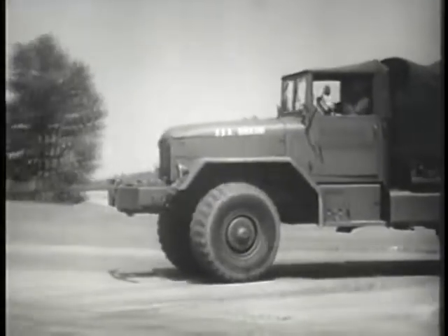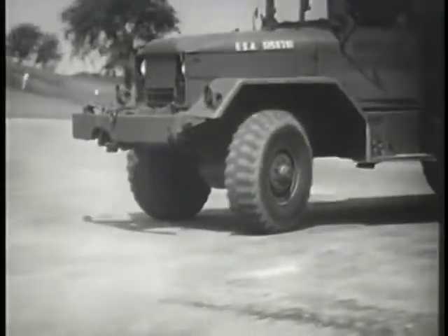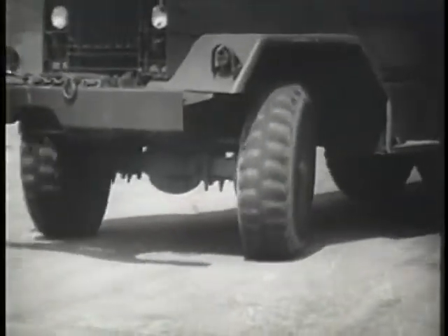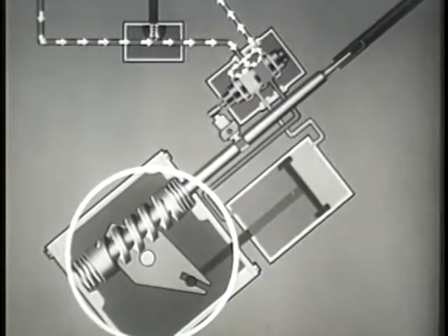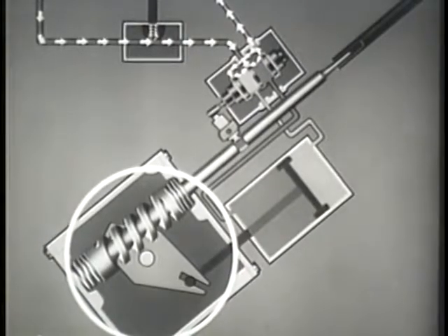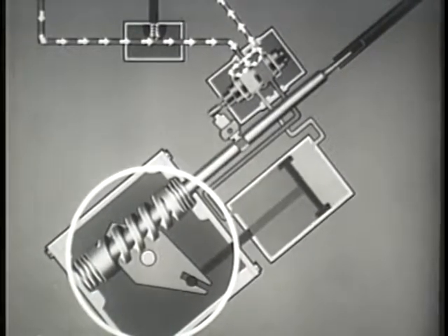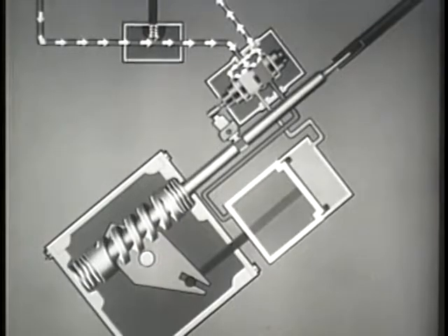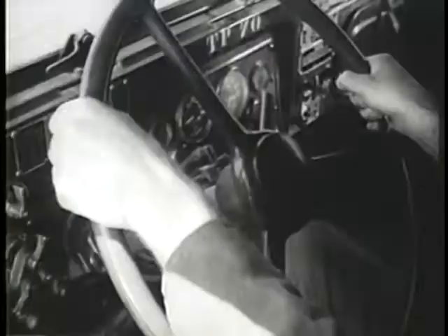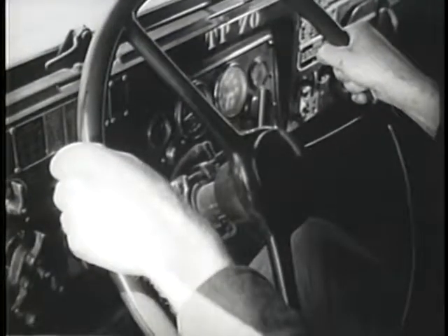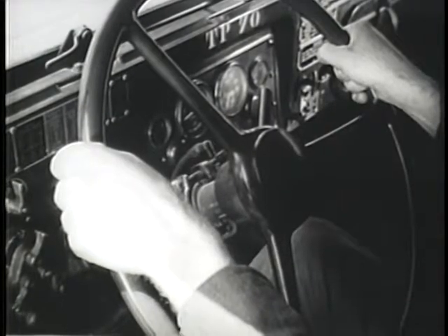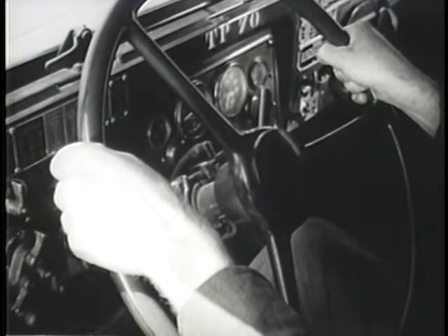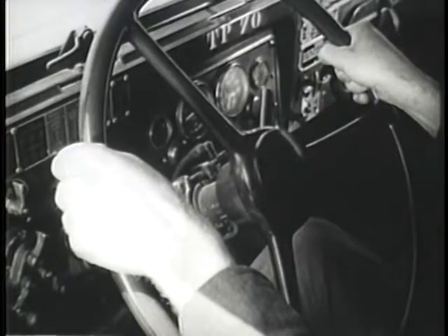When the front wheels are held in a constant turn, the cam will not be rotated. The Pitman arm shaft lever is held stationary toward one end of the steering cam by the increased pressure on one side of the piston. The tendency of the steering geometry to return the wheels to the straight-ahead position is overcome by the driver, who maintains a constant force on the steering wheel in the direction of the turn.